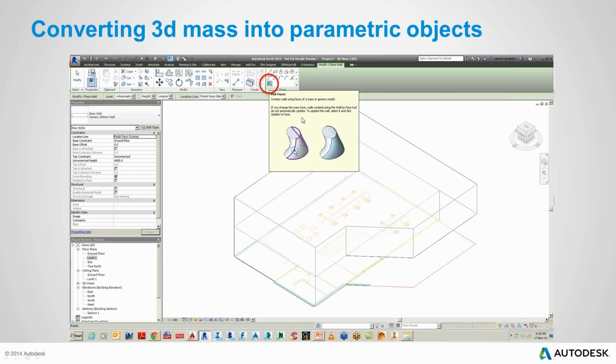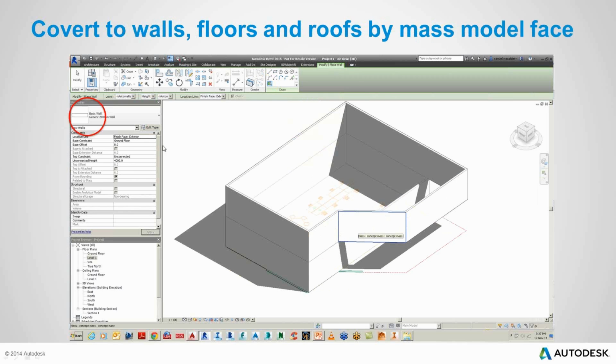For those of you who maybe want to work with more complex shapes, you can start to set up maybe ellipses or curves, and you can create shapes on certain levels, and then you can create solid forms or geometry between those two shapes assigned to the different levels. So there's all these different ways you can start making conceptual models within the Revit interface. So in this case, I've just gone through that line workflow, and I've just got the perimeter of my building, and I've assigned some walls to each of the two levels for this small architectural office that I'm designing.